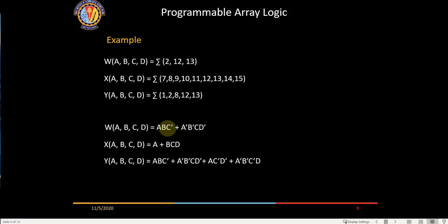So these are the functions. Okay, A, B, C dash, right? Now if you see this third one, Y, these functions are already implemented in W, so I can write it as W out here. This has got 1, 2, 3, 4 AND gates it requires, but this has already been implemented by W, so you can write it as a W, and then these two. Okay, is this aspect clear? Then we'll see the implementation part.